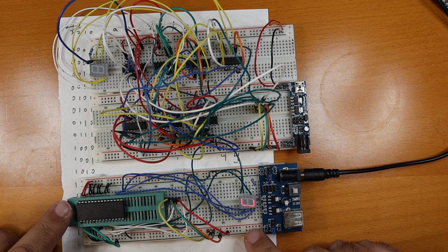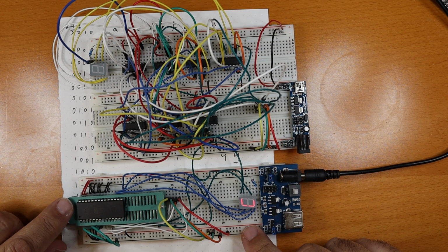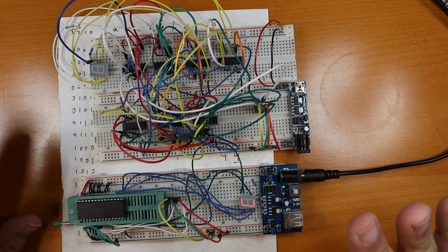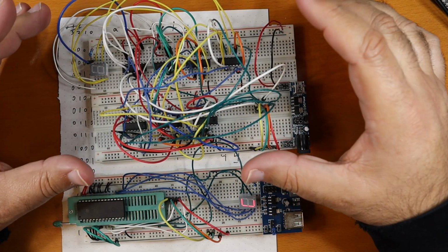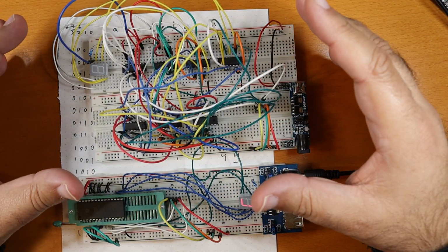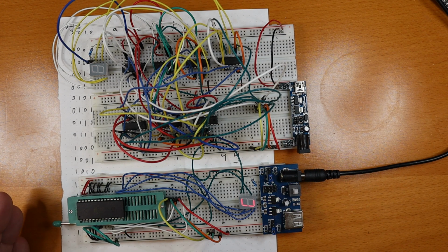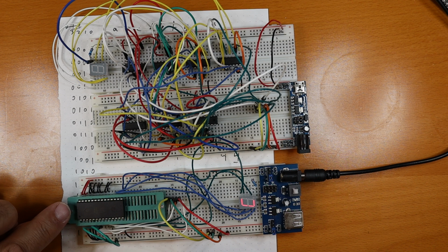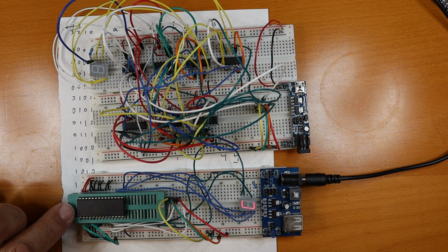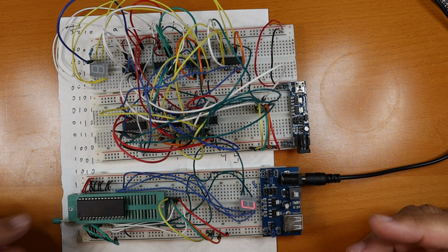The other downside is the amount of transistors here. Now, if you think about it, this makes sense because here the logic is implemented with this rat nest of wiring. Whereas here, everything is laid out and programmable, but there's logic that needs to do the address resolution, and that logic requires a lot of transistors.